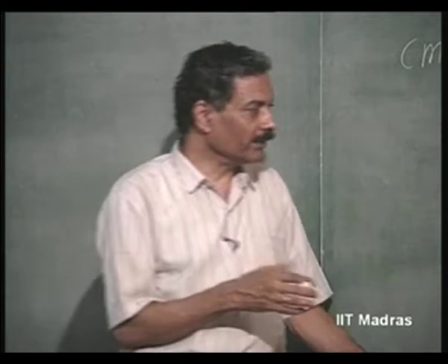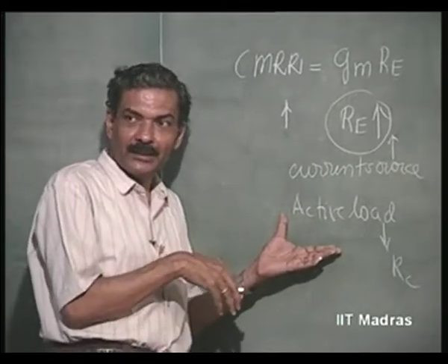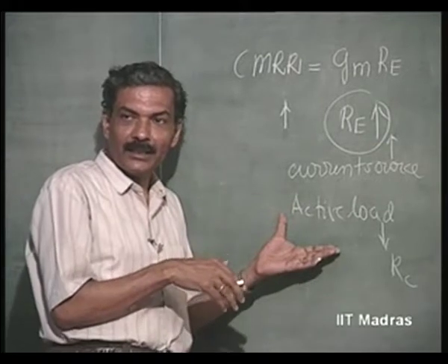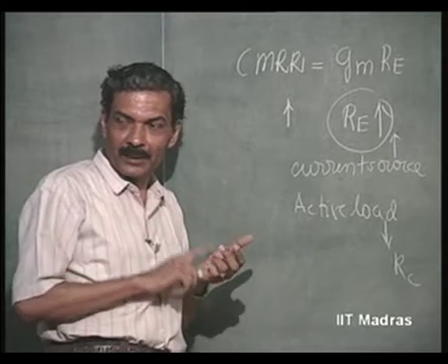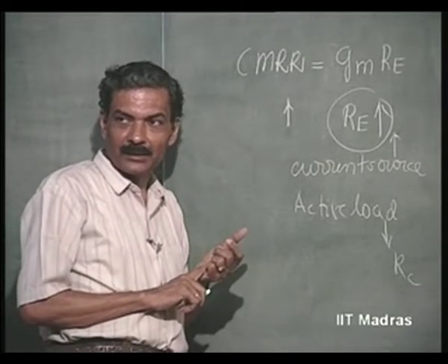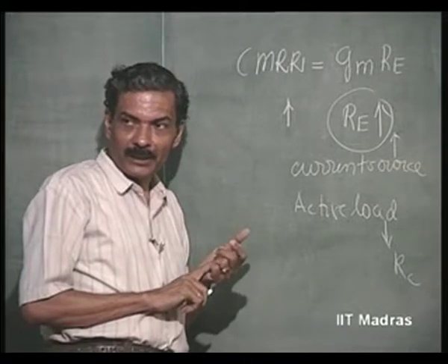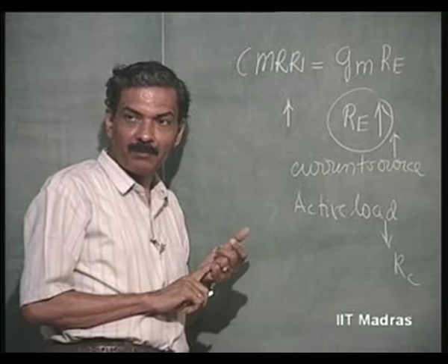Therefore, this kind of structure, which performs better and takes up lower area, is highly suited. Not only that, it solves our problem regarding common mode swing and common mode rejection ratio, and it solves our problem regarding reaching low valued currents without using high valued resistors, which take up a lot of area.